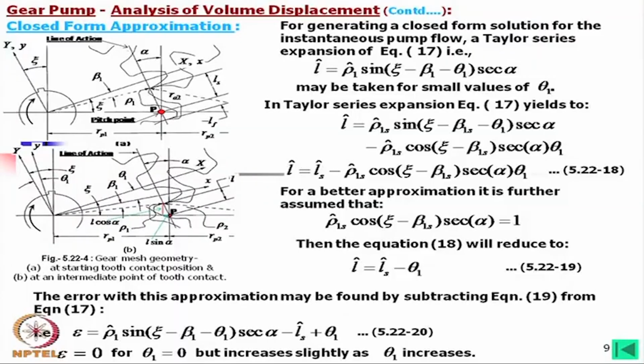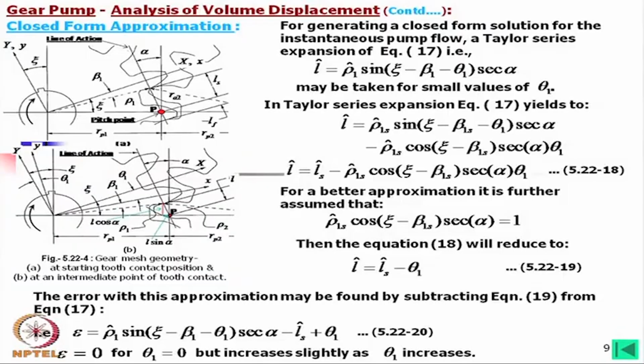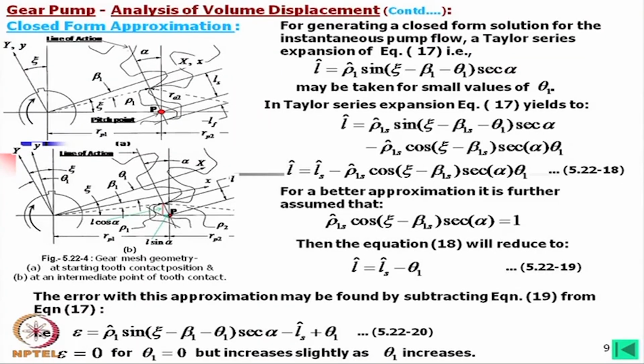Just one pitch rotation, actually not even one pitch, one base pitch you can say, and for that the total rotation is equal to 2 pi by z, and z is usually taken maybe 20, at the lowest maybe 10, not less than that, at least I have not seen.